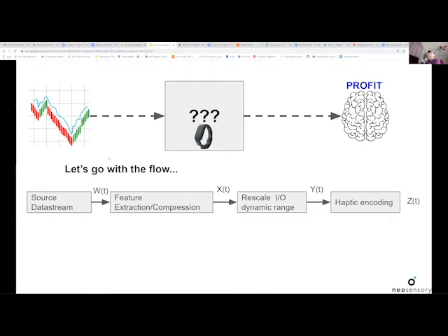There are other ways you can do it, but let's just say we have our source data stream that the Buzz is picking up. Then comes the processing, whether you do that processing on Buzz, which we do, or through a peripheral device like an Arduino or a mobile phone connected over Bluetooth Low Energy. You need to take your signal and get out of it only the key information that you care about. You might not care about all of the data in that signal.